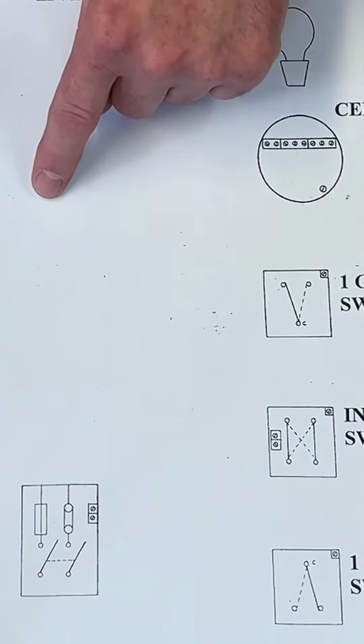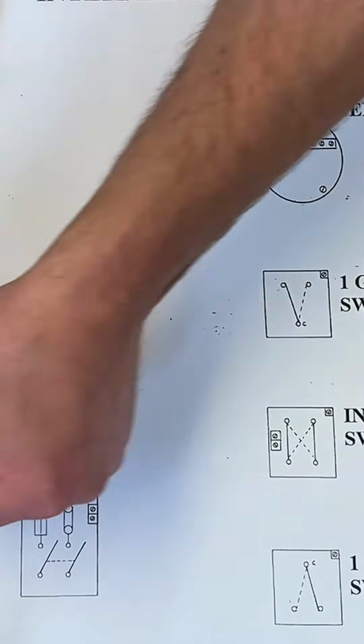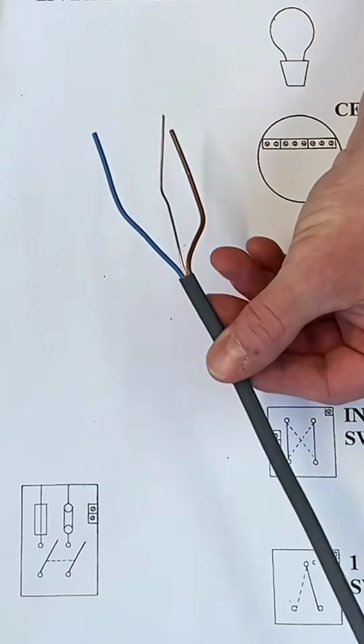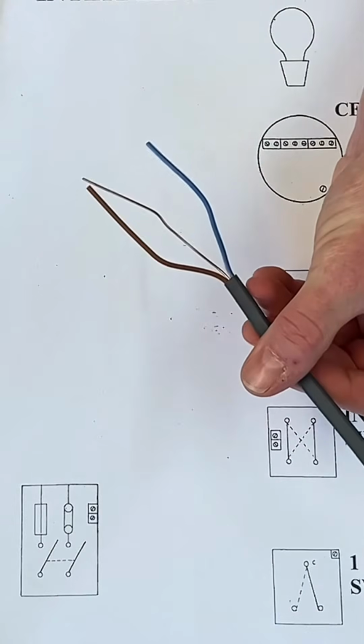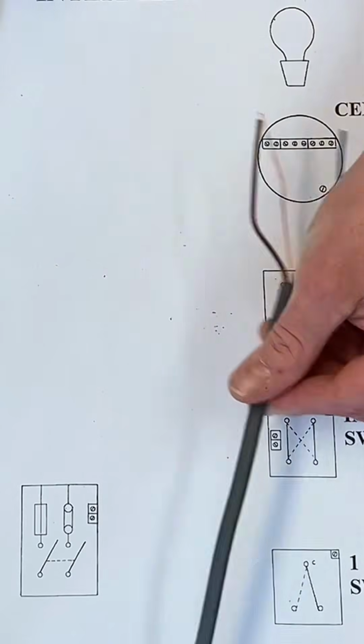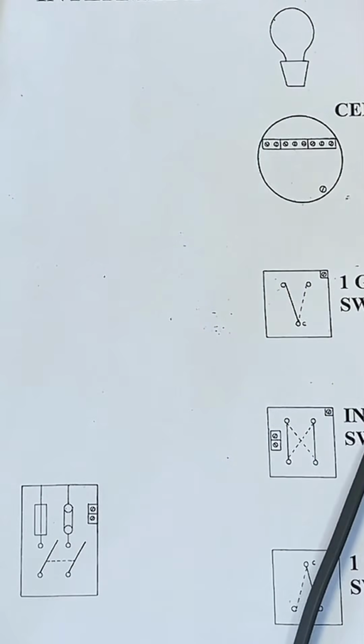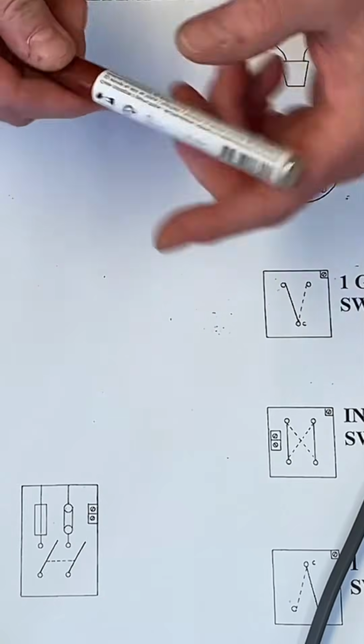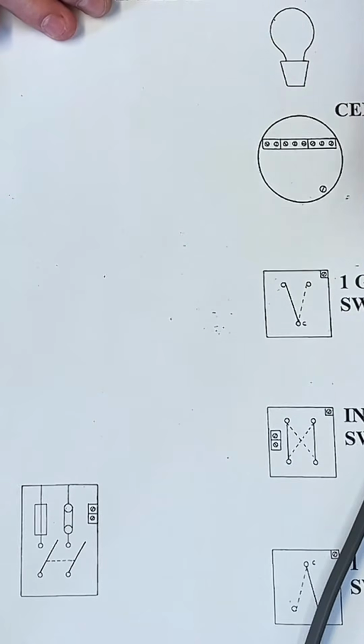We're going to bring a cable from the consumer unit to a light fitting using 1mm squared PVC twin and CPC cable. So we've got a line, our neutral and a circuit protective conductor. We'll put those in first. Remember, you will be using a rule. I'm not, I'm going to do it freehand, and I'm also doing it upside down.